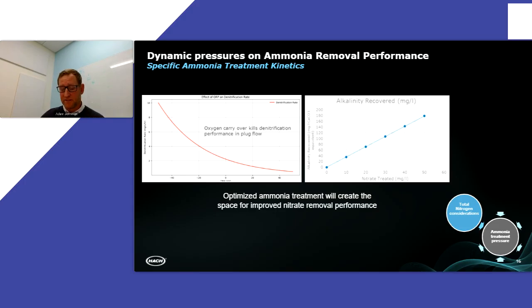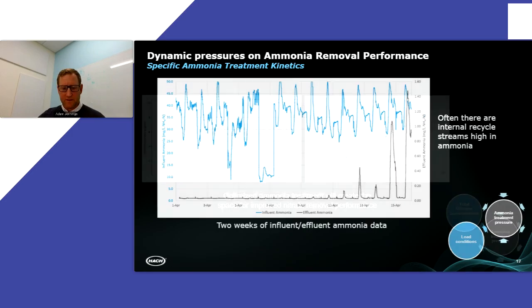And the other bonus to that is if we are doing that process and we're bringing that nitrate-rich liquor back around and we're doing some denitrification, we're gaining a little bit of alkalinity. So we're putting a few credit points onto our aerobic system to help maybe increase or have better or more stable nitrification. We win in both ways when we do it that way.